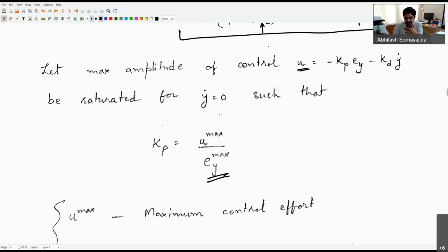So we are making sure that our controller gains are tuned using design parameters such that we are not seeing them go beyond certain practical limiting values. And that is why we introduce these parameters. Otherwise, I could have simply said that I'll choose Kp to my liking. We are not doing that, and we are specifying it in terms of U max, specifically so that the control input doesn't ever go beyond that value, more or less.